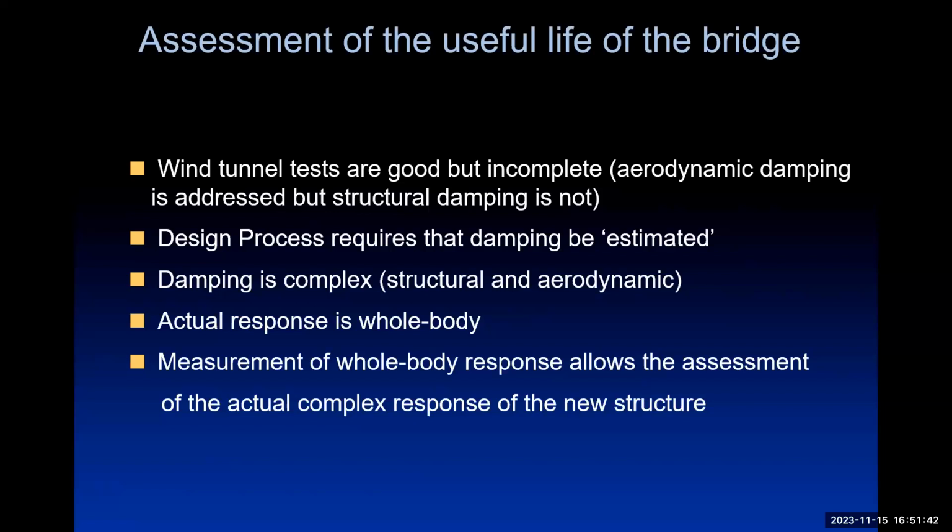So, general assessment of bridges. Firstly, wind tunnel tests are good, but incomplete because aerodynamic damping is addressed, but structural damping is not. The design requirement actually requires that damping be estimated. So you do all of these tests in a wind tunnel.